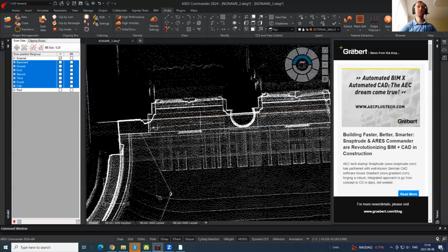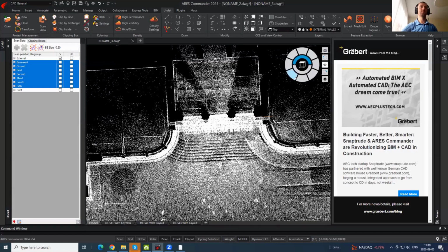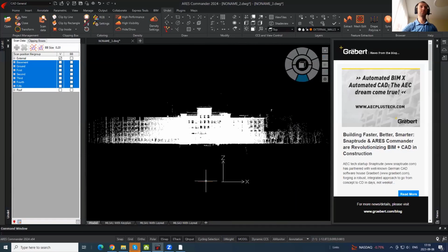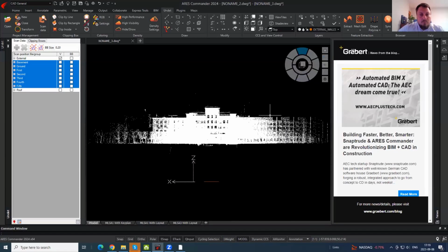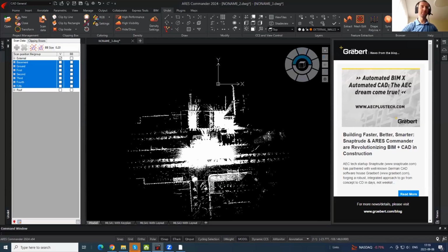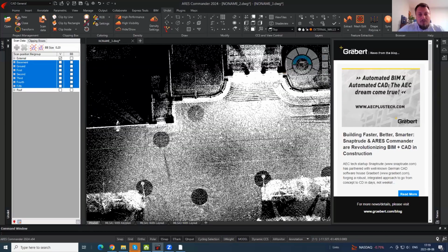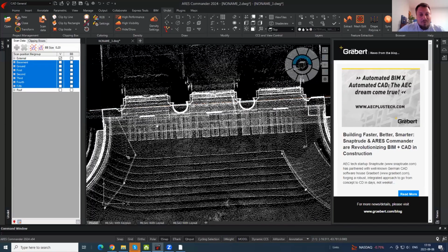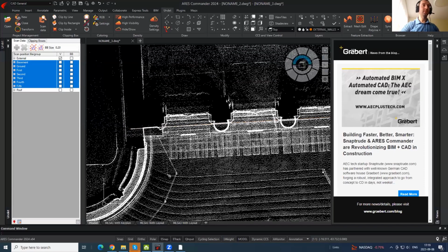When drawing, I use only UCS to have all the lines at the same elevation, because from the top it looks the same, but when you switch to the front, lines could fly here and here and here. It's not good looking. So you are recommending not to snap when doing the floor plan vectorization or elevation vectorization, yes. You can make mistakes.